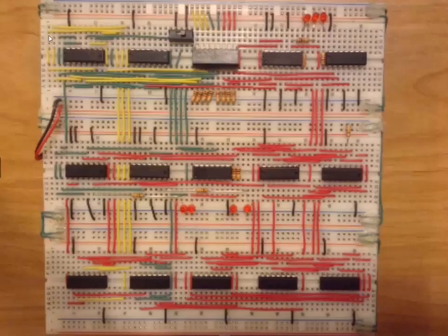So this is the circuit that I built, and I've tried to keep the colors identical with the schematic that I showed you before, where the red still represents the 3-bit letter B inputs over here, and where the red also has the half adder, the two full adders, and then the green representing the load button, the add button, and the push button, and then finally the yellow representing the first set of inputs, which is the letter A.